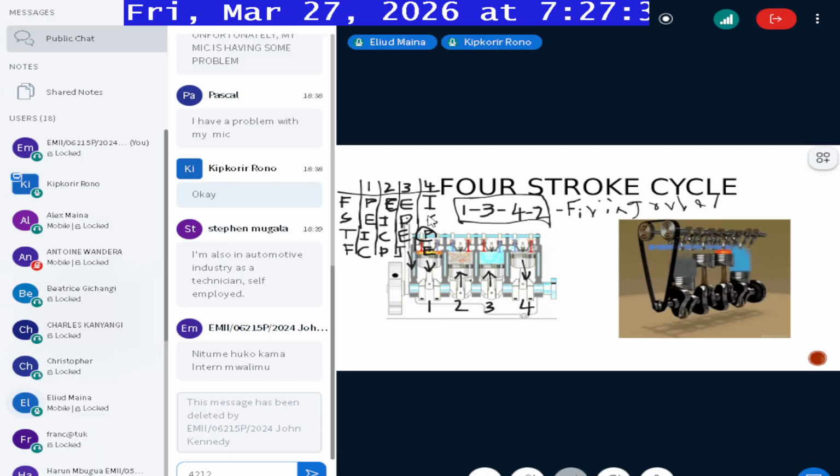Yes. Could you repeat your question? Yeah, so I need you to produce a new firing order based on a new arrangement. So I've switched, if you see this one, initially we had power here, and for cylinder number 2 it was exhaust, compression, intake. Now I have switched it to power, compression, exhaust, intake. So you have the first line. I want you to fill the other 3 lines, this one, this one, and this one, and then produce a new firing order.